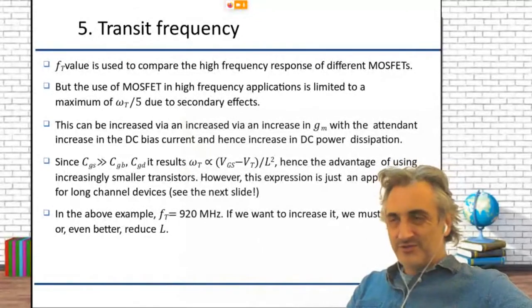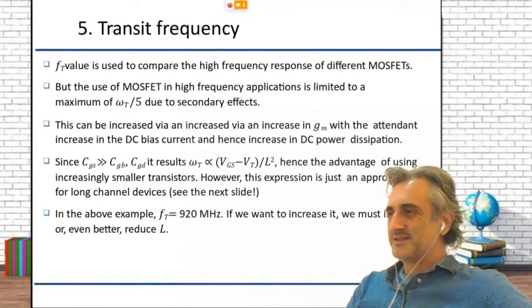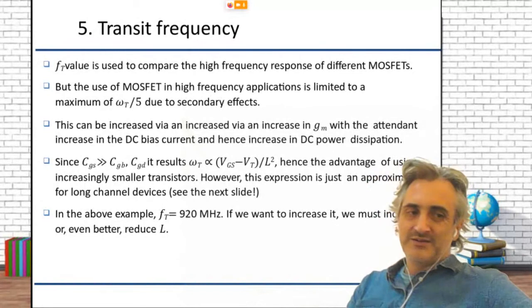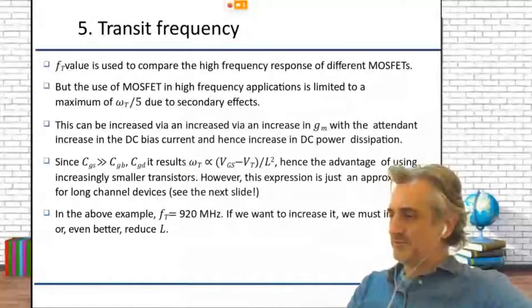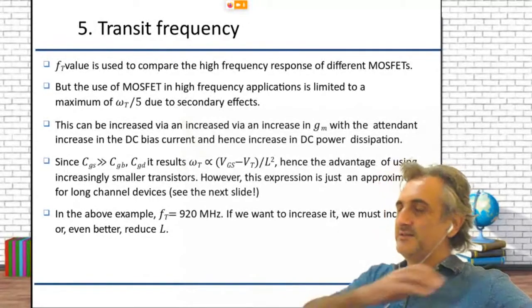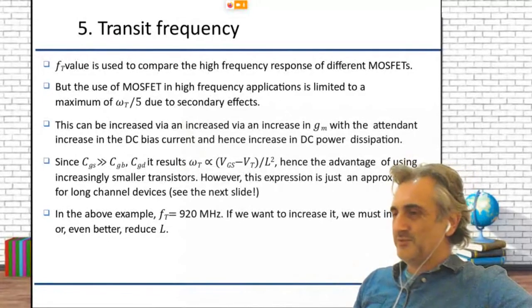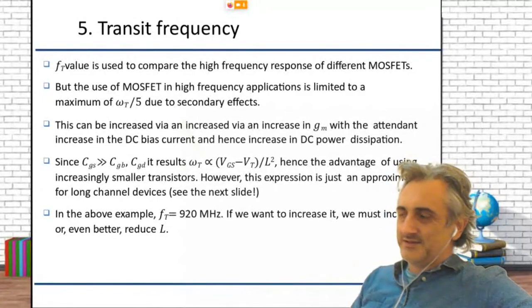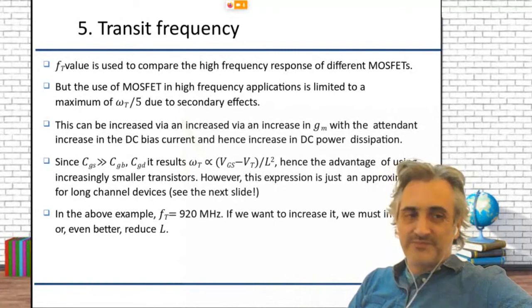So in this aspect, these transistors would be correct to work with FM frequency, with FM modulation, at least for the first stage. After the processing, after the LNA and the mixer, they would be okay. But 900 megahertz is not very fast.